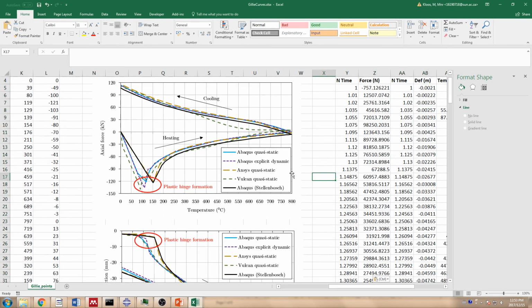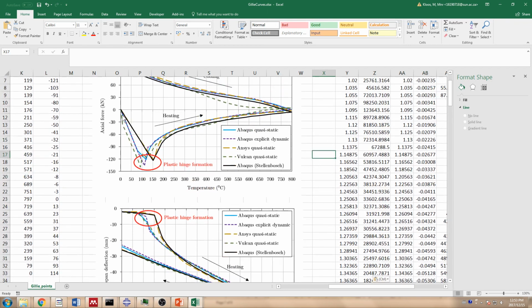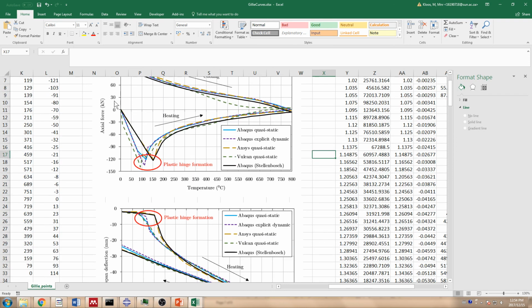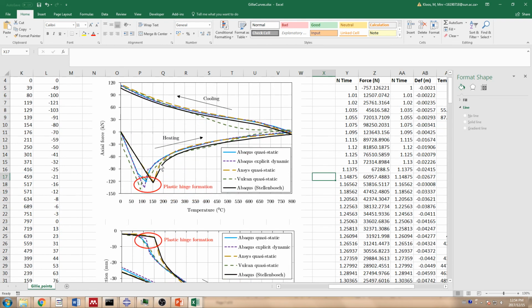Cool. So if I do that, you can see how the result matches the ANSYS results much better. So it's possible that when the original benchmark results were done, they applied their boundary conditions differently. They applied 2 springs instead of 1 spring. And the reason for the difference, I think, is that 2 springs in series actually change the stiffness. So you can see how the slope is less, which means that there's less of an axial force at a certain temperature or a certain expansion. So this might be one reason why those 2 results are so different.